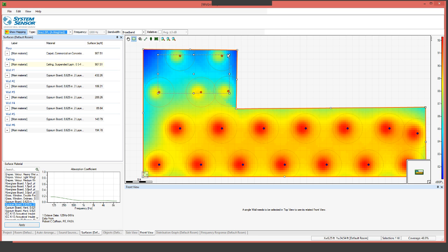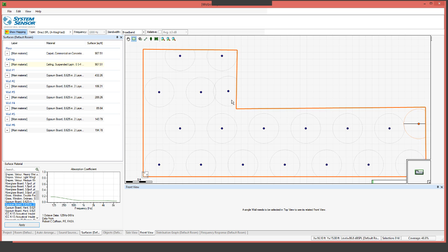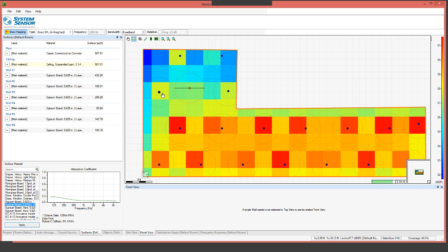You can see here where I changed the type of a device from the high volume that the rest of them were to the low volume, that I have lower volumes in that part of the room, even though these devices are mounted at the same level. And I can then also in this view move things around to fill in the spacing better and adjust these manually if I like to, just by clicking and dragging.